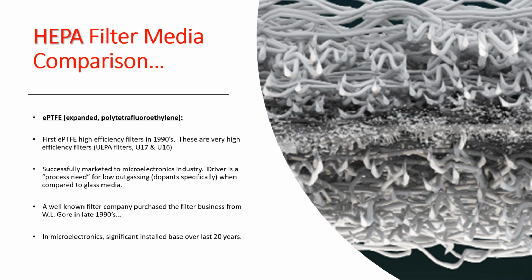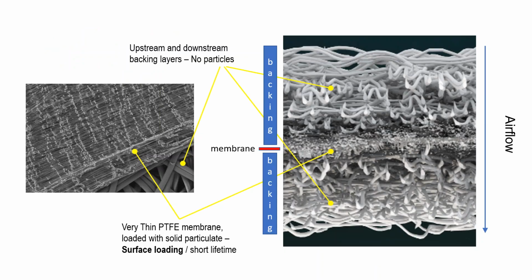Since then, a well-known air filtration supplier has purchased, or was purchased by, a company who purchased the rights to ePTFE. And so they've been pushing it a lot, especially in the life science or bio space. The challenge when it comes to PTFE is its efficiency as a result of its construction. In the way that glass filters through depth filtration, PTFE does not have the ability to do that. It is a razor thin membrane.